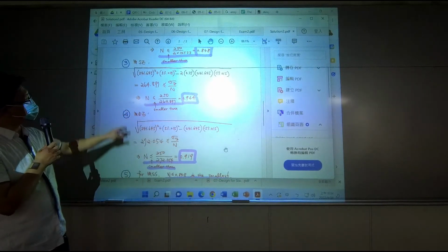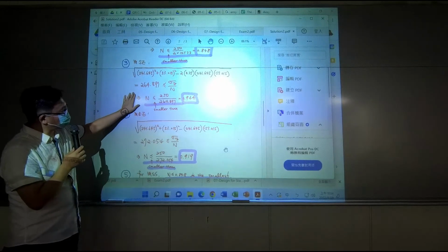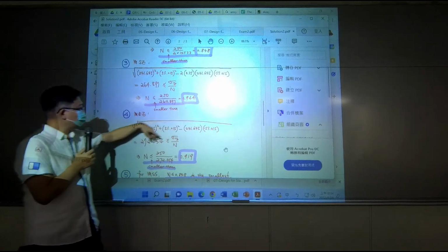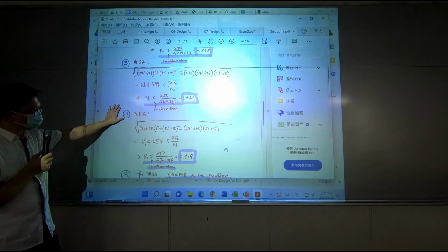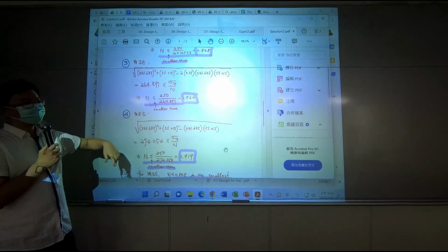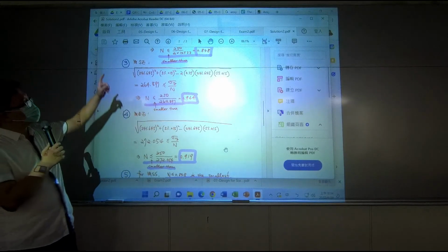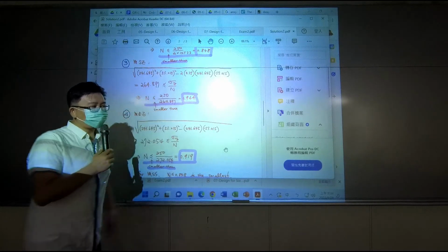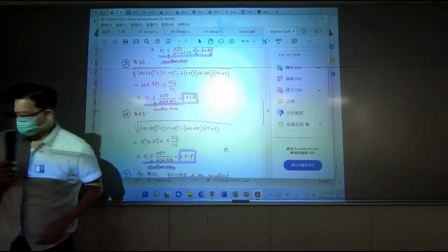So at the end, if you use maximum strain energy model, you will have a greater safety level. If you use distortion energy model, you have a safety level in between. So it means the first model, maximum shear stress, is the most conservative one.